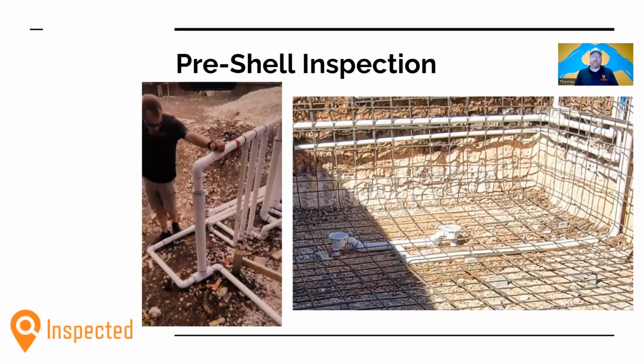So on the picture on the right, you can see that the builder used 3-inch pipe, and they just ran it down the side of the wall and across the bottom of the pool. And then I guess the plumber didn't have 3-inch elbows because they tapered it down to 2-inch on that 45 curve on the left and the right side of those T's, and have effectively bottlenecked their pipes so that it can't move more than 84 GPM, which is the maximum for a 2-inch pipe. So that's a lot of money on a pipe that is only limited to 84 GPM. So consider that in your fittings.